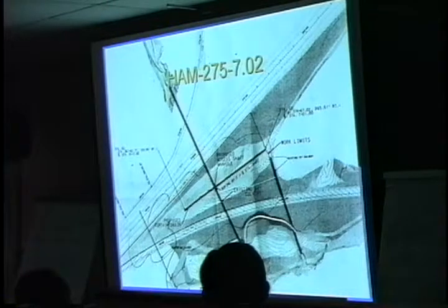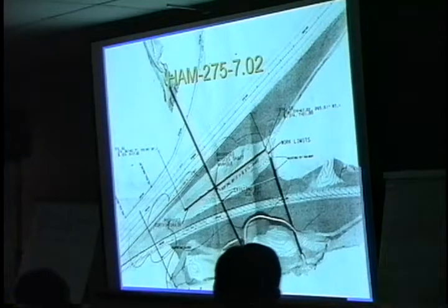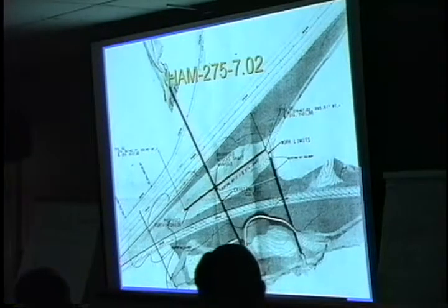After a lot of investigation, we decided to put in this curtain drainage right here to cut off all the drainage coming from this direction that was causing this failure. And also some drainage was put across the road to cut off any water coming down the granular base of the roadway.